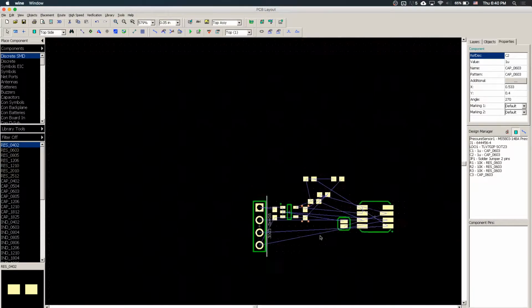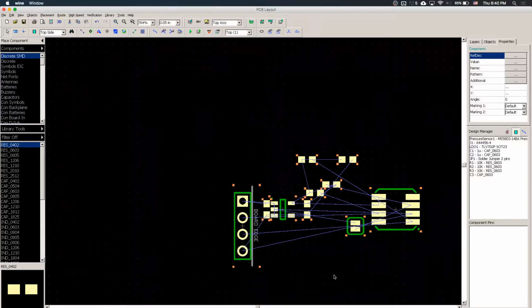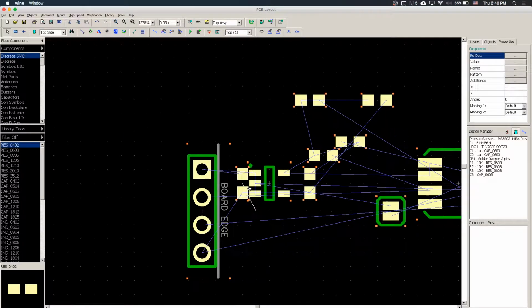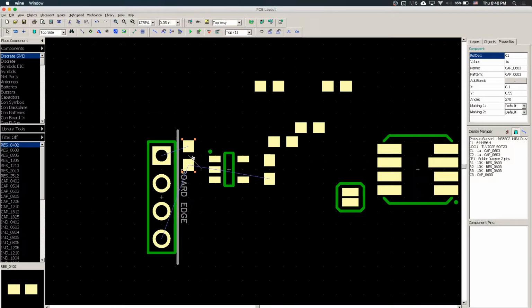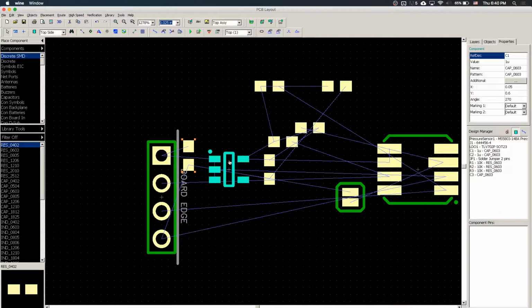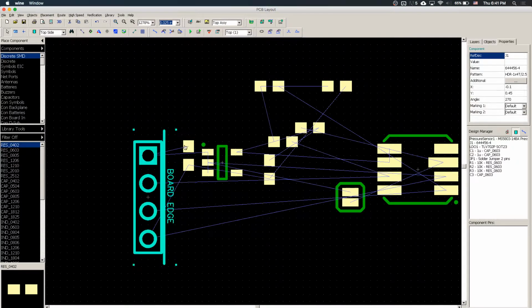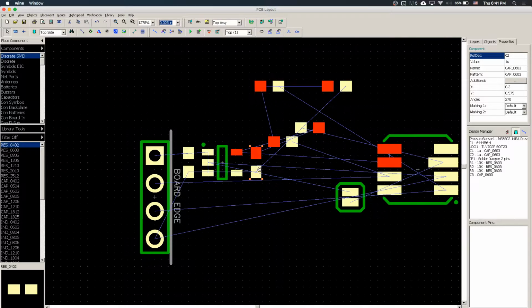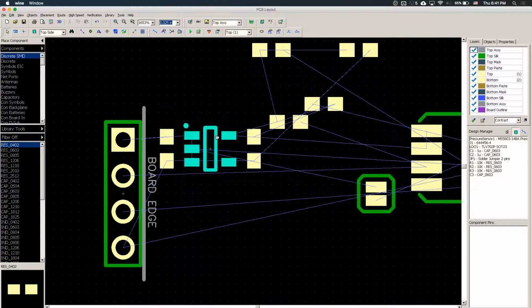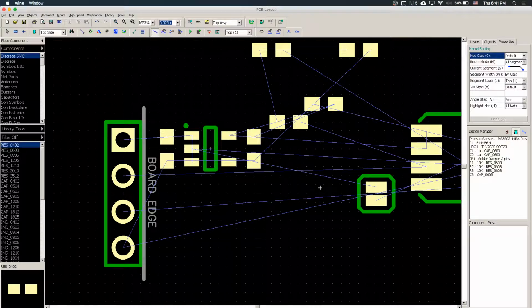One thing I would like you to do is select all your components, and snap to grid by the origin instead of by path, so that will make aligning all your components much easier for you to do. And so in this case, we can start using a smaller grid to make all your components fit better. So we're gonna do that. Capacitor here, like that, and what we're gonna do is we're gonna hand route our stuff.